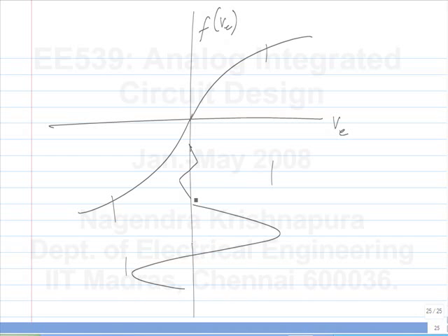Is this part clear? I am saying with feedback, you are reducing some part of the input. Basically, you are subtracting something from the input. So, the amplitude to the input of the nonlinear block is smaller. So, effectively, the nonlinearity, you can expect it to be smaller. Is that a reasonable argument? Okay or no? Okay. So, now let's go to the next part, which is more interesting.